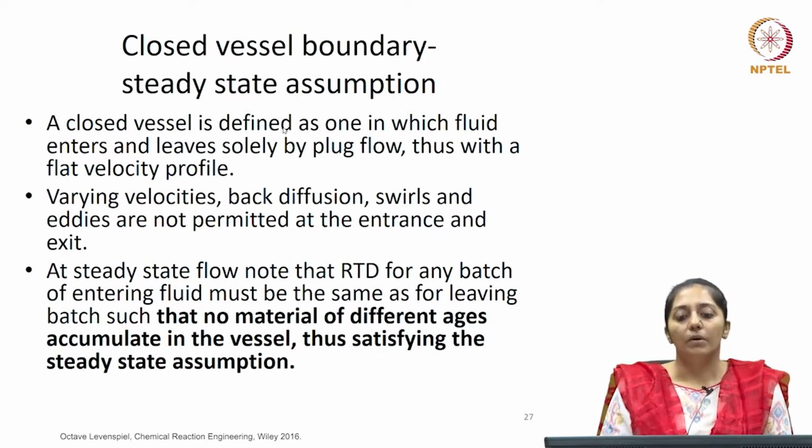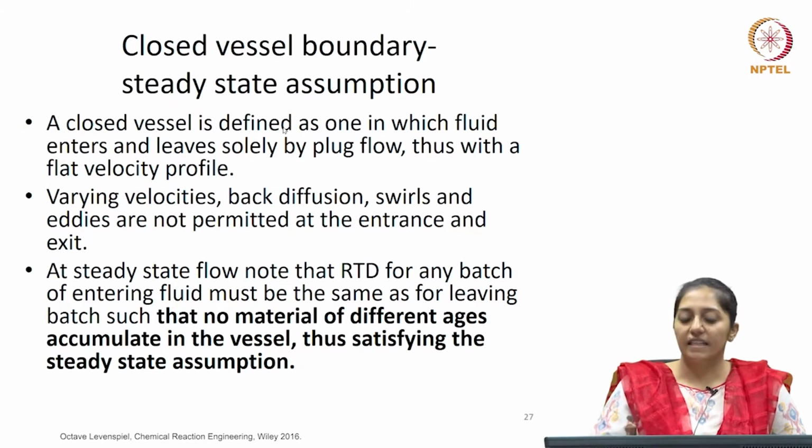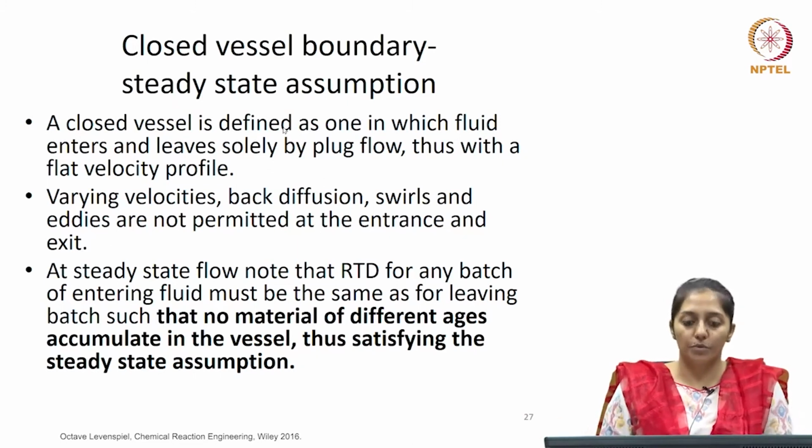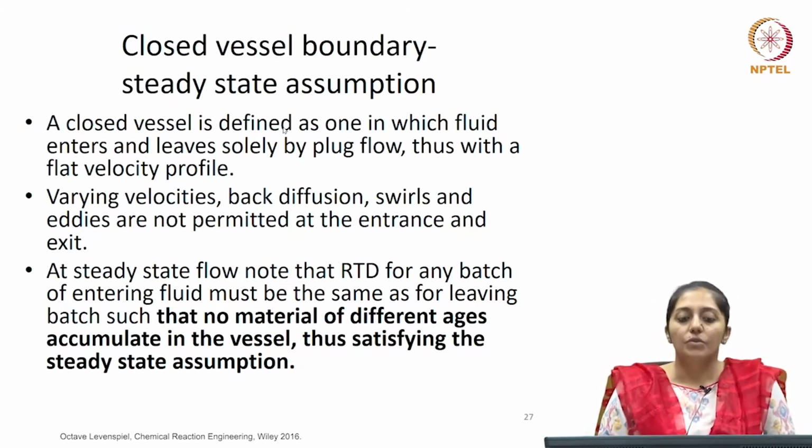Now we will talk about the steady state assumption, or the closed vessel boundary. A closed vessel is defined as one in which the fluid enters and leaves solely by plug flow, thus with a flat velocity profile, which means there is no velocity gradient. Varying velocities or back diffusion, swirls and eddies are not permitted at the entrance or at the exit.